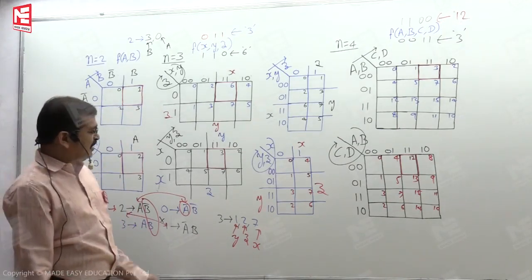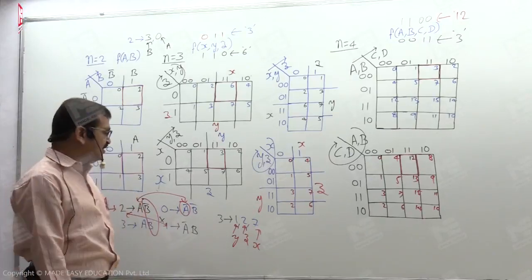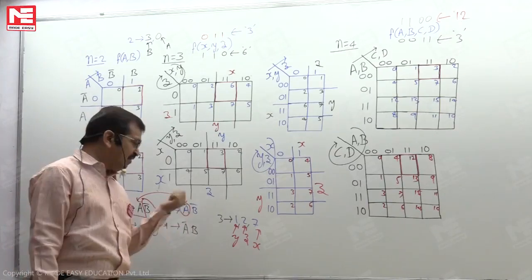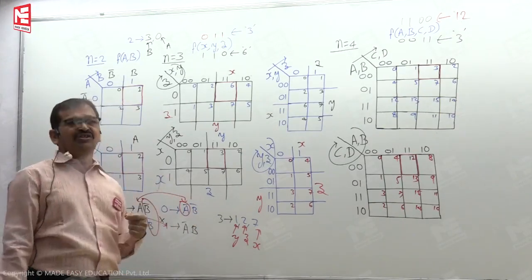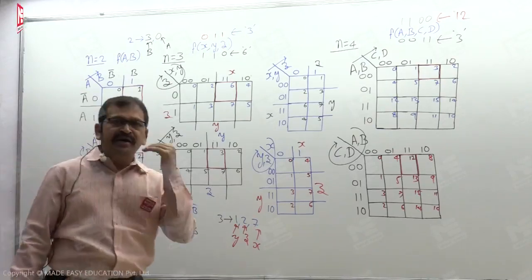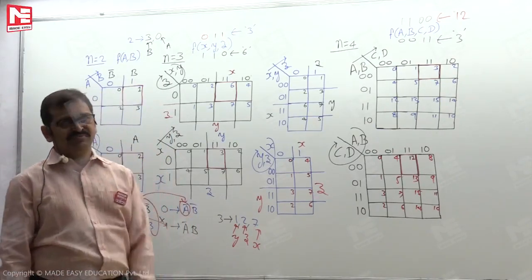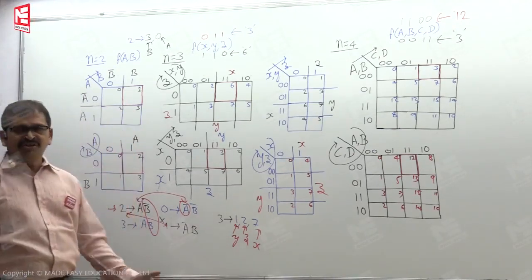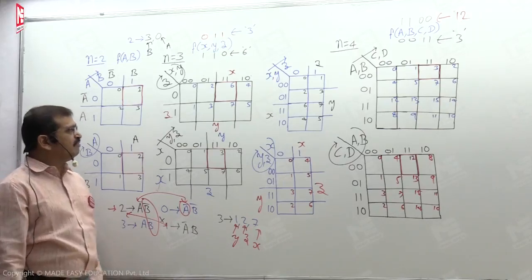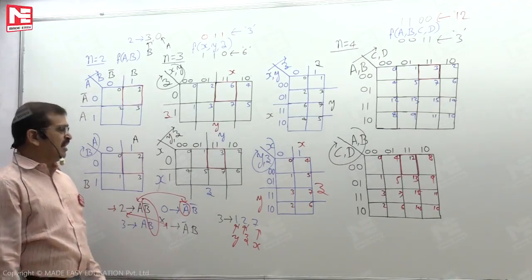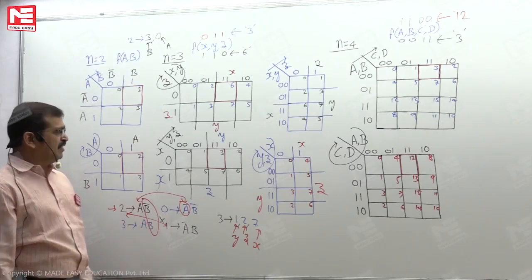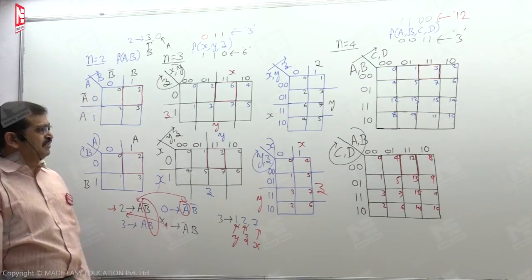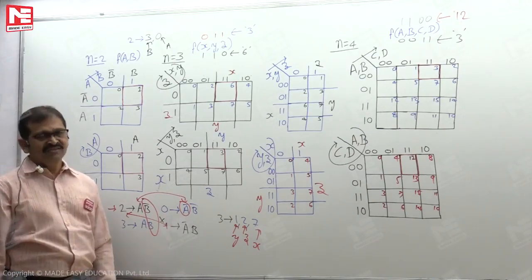So with any other cell product, we are not reading any other cell as an adjacent cell to cell 3. As long as our reference cell is 3, these are the only 3 cells which will be read as adjacent cells. So like this, in this 3 variable K-map, for every cell we look at, there are exactly 3 cells which will be adjacent cells.